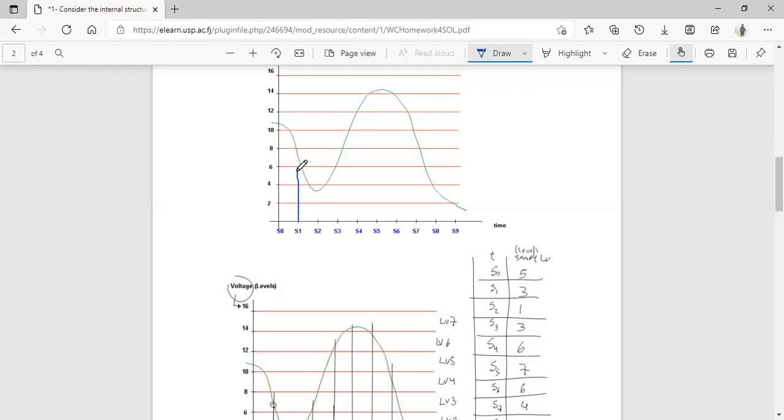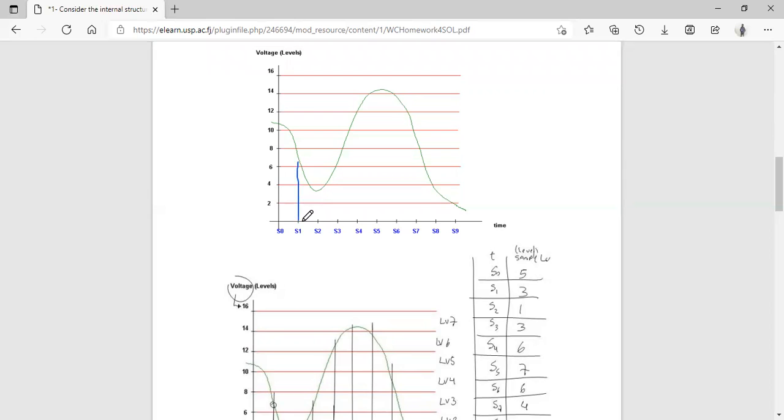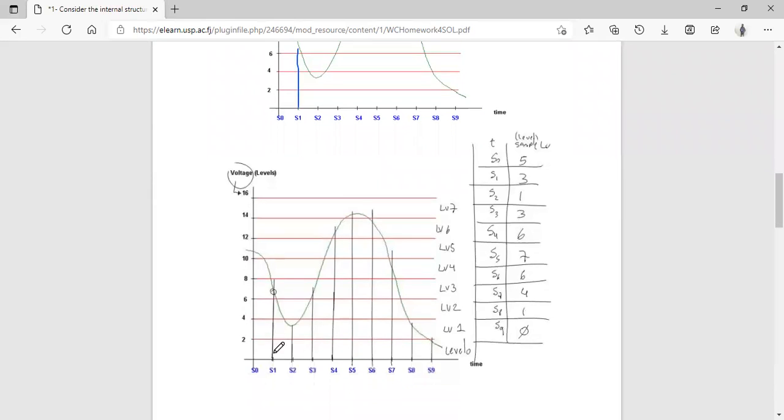So basically you draw a line, right? If you draw a straight line, you'll end up with something like this. What this means is at each sample, at what level does this particular signal fall in? Like in our analog signal, if we have 2 to the power 3 bits, it starts from 0 and goes up to 7. That's the maximum value, isn't it? Same goes over here in our PCM system. You start with level 0 and go up to level 7, so that makes up a total of 8 levels, right?